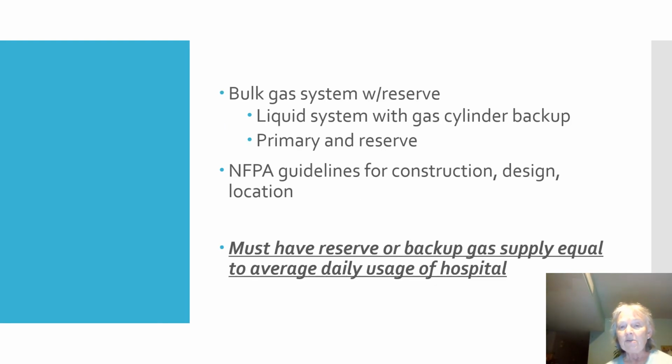And there you can see the bulk system, gas system with a reserve. You can also have the liquid system with a backup liquid system, or a liquid system with a backup gas system if you want to. So the National Fire Protection Agency has the guidelines for construction, design, location, and there it is. You have to have reserve or backup equal to the average daily use of your hospital.